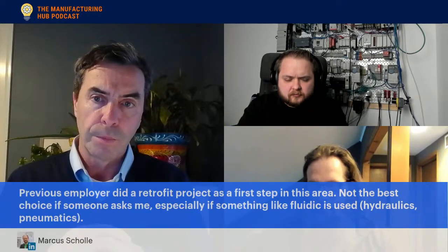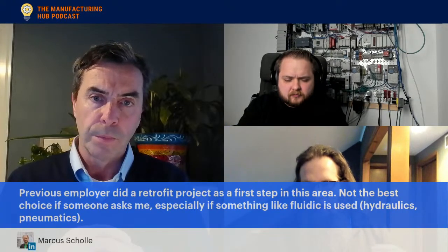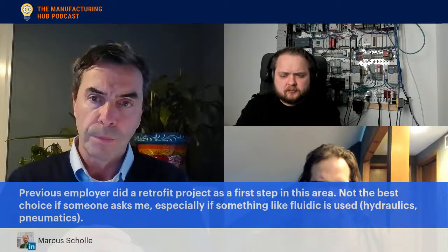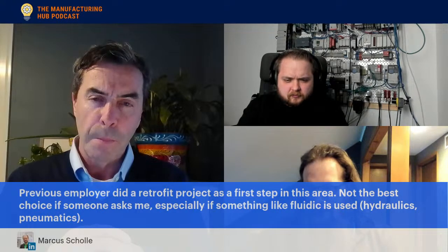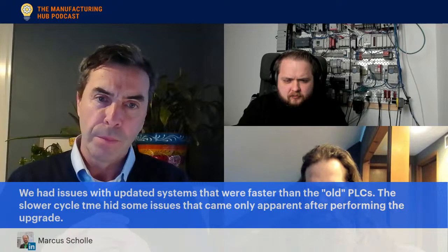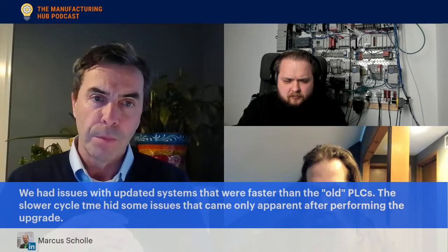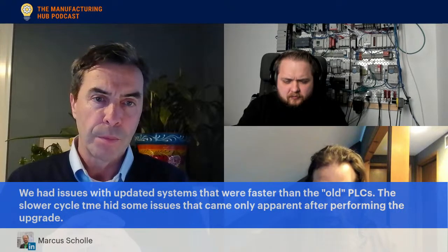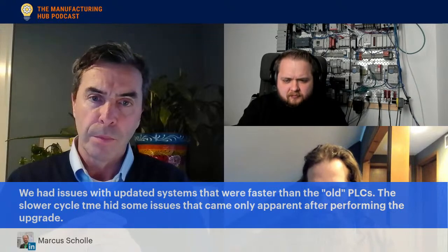And Marcus is in the chat talking about a previous employer that did a retrofit as the first step of a digital twin. Maybe not the best choice, especially with something with fluids such as hydraulic and pneumatic. And then Marcus was also talking about how they had issues with updated systems that were faster than the old PLCs, and the slower cycle time hid some of the issues that became apparent only after performing the upgrade.